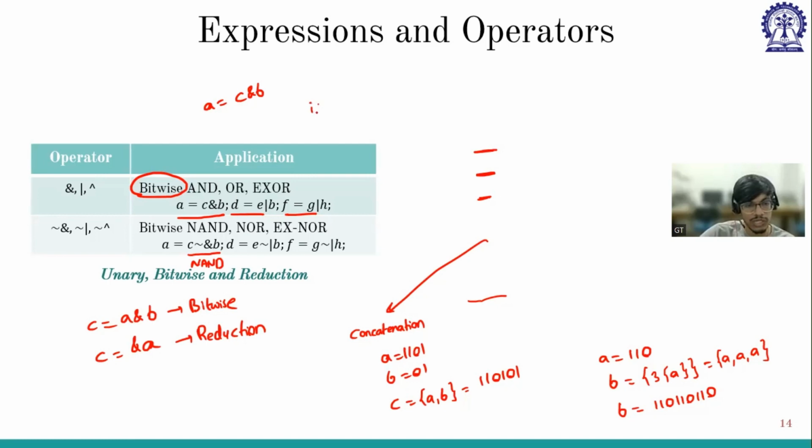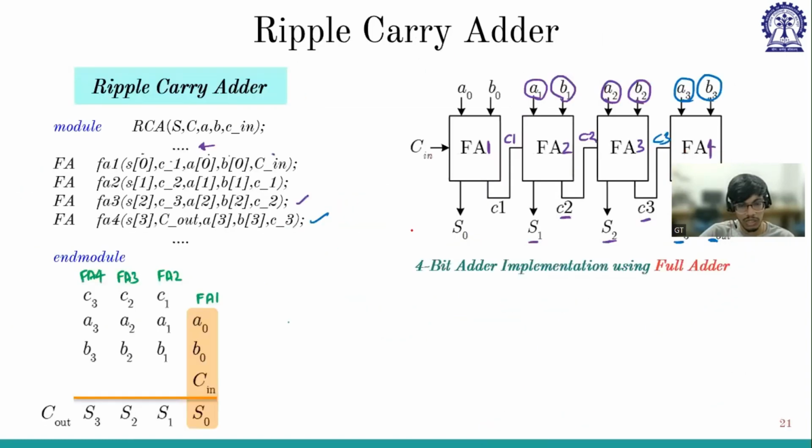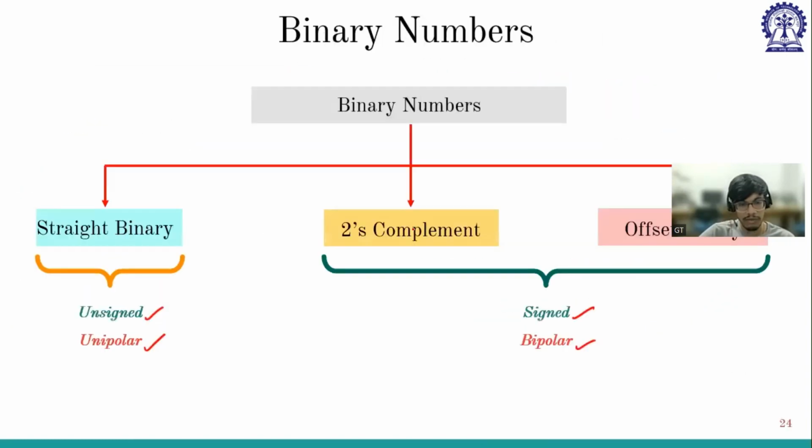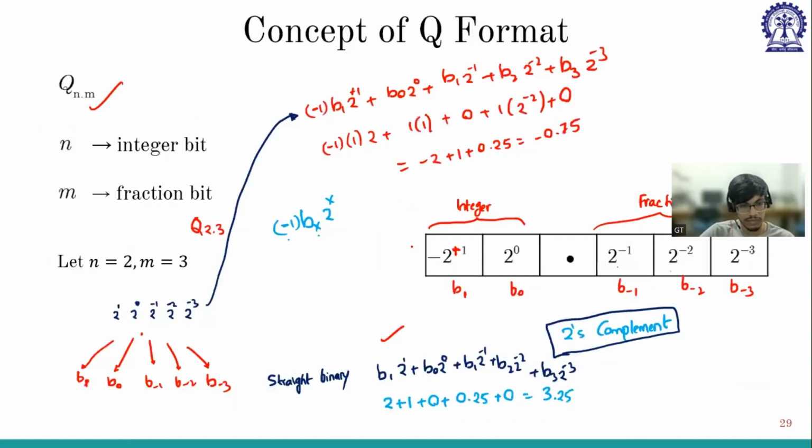But if you are using it inside a condition, if A and B, which means if A and B is equal to 1, you can write it in this way. So in the logical operator only, we will use two ANDs. Else, in any combinational logic, we will use a single AND. So here we are doing only combinational logic, so that's why we are using a single AND. But if it is inside an if, then we can use two ANDs.